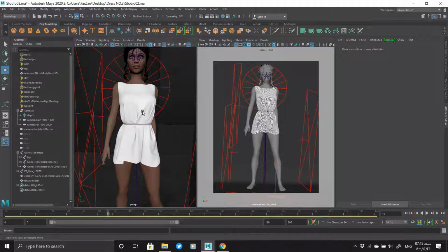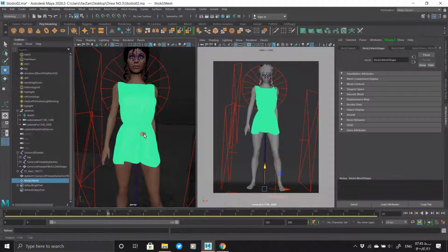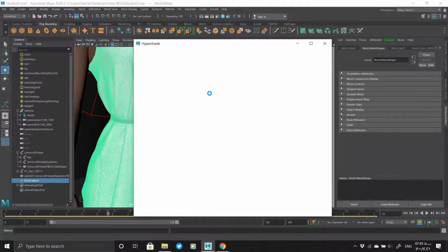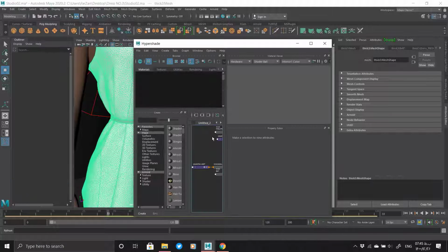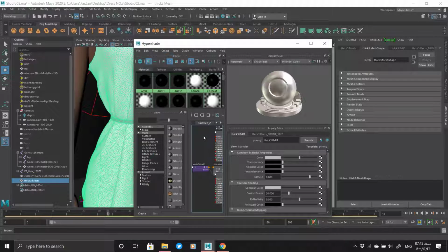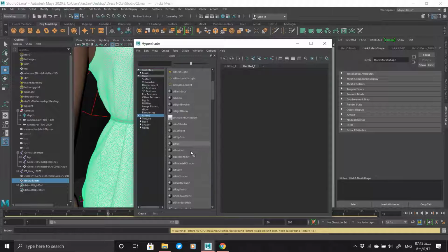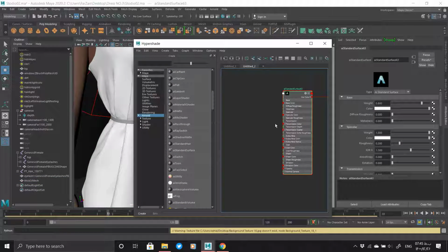We enter Maya and enter the low poly model into the studio. And after placing the camera and adjusting the lights, we start importing textures, and in the Hypershade, by creating an aiStandardSurface, we start connecting textures to each of our parts. Different nodes may be used, including bump2d, displacement shader, divide. Then we attribute the made material to the model.